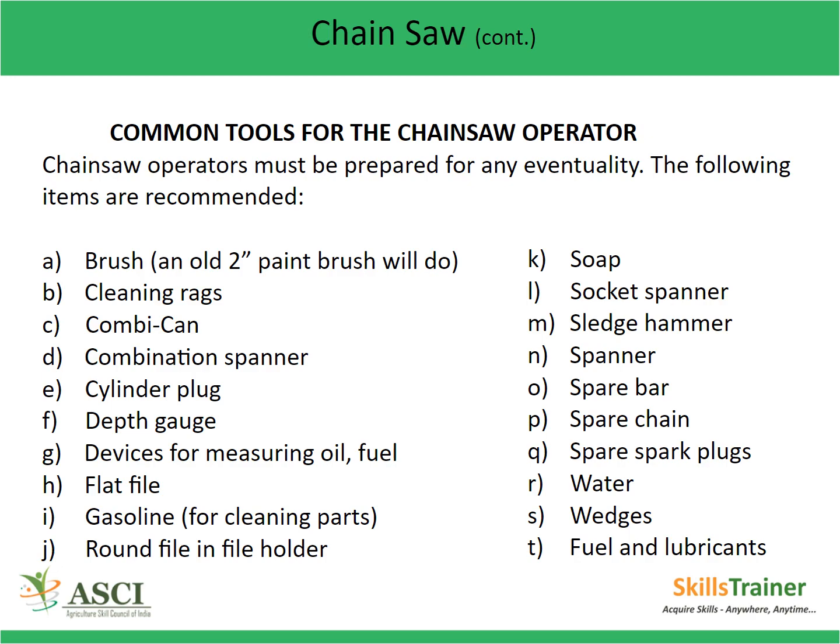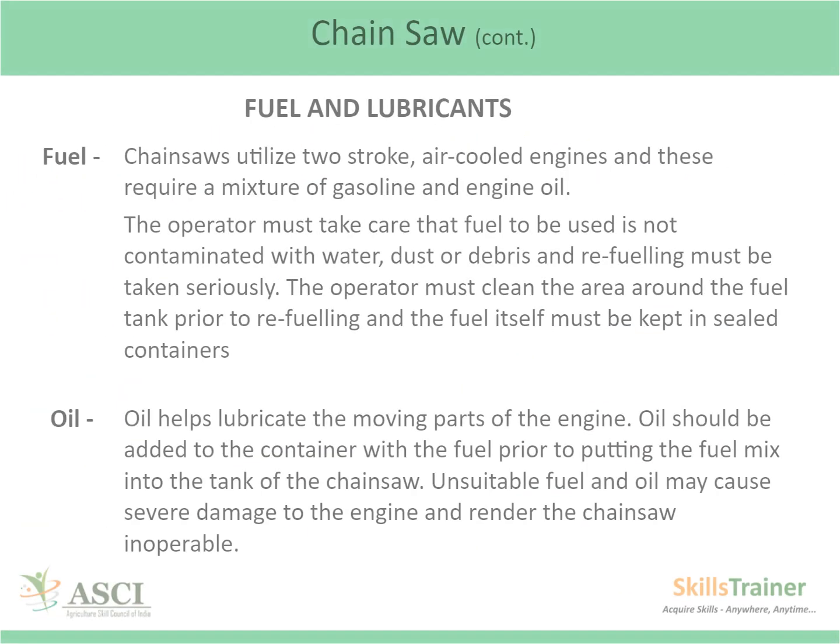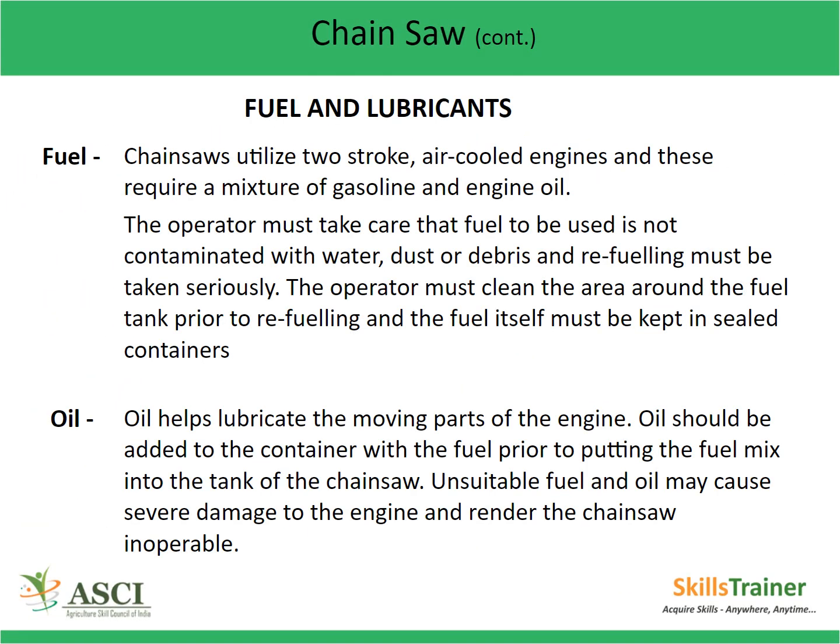wedges, fuel and lubricants. Fuel and lubricants. Fuel. Chainsaws utilize two-stroke air-cooled engines and these require a mixture of gasoline and engine oil. The operator must take care that fuel to be used is not contaminated with water, dust, or debris, and refueling must be taken seriously. The operator must clean the area around the fuel tank prior to refueling, and the fuel itself must be kept in sealed containers.